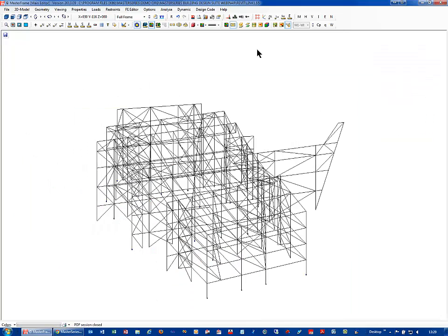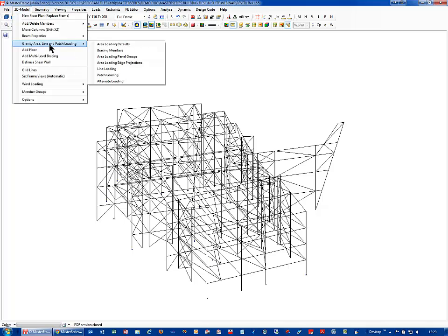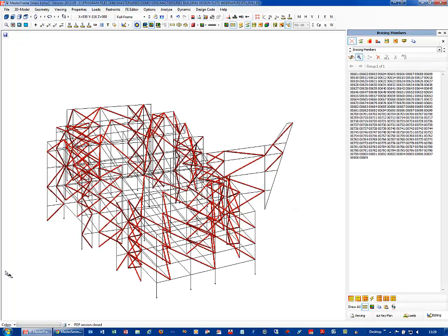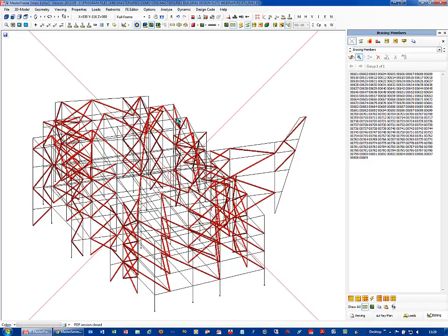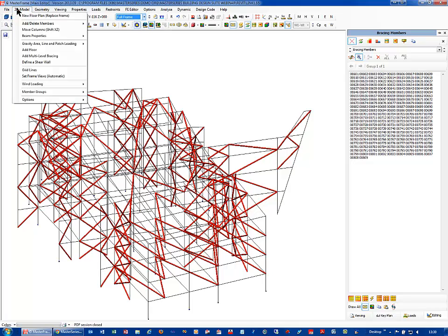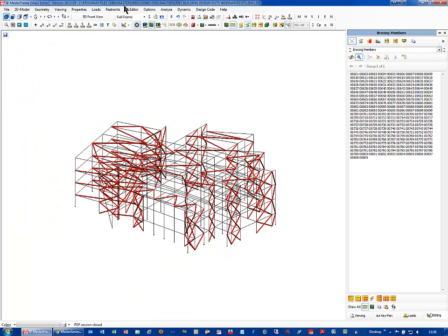I mentioned earlier about bracing, and bracing is very, very useful. Obviously for the structural component of the building, it makes it stand up. But from our point of view, bracing also allows us to distinguish which members are used for spanning the floors or the walls, and separately then which ones are used for bracing. So if you can imagine down here, if we go to say, well, let's just create all our default zooms and then go up to plan level 1.